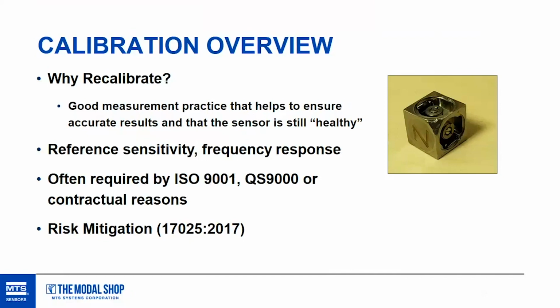On the right there's a nice little picture of an accelerometer that's been through some things in its life. It's had some rough days. It's missing a couple of the weld caps, the base is a little bit bent, and there's definite marring on some of the surfaces of that triax. On those two open faces, you can actually see two of the sensing elements for two of the axes in the triax. So that one obviously has been through a lot, and it's pretty easy to see what's wrong with it.